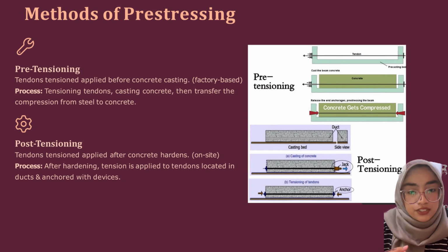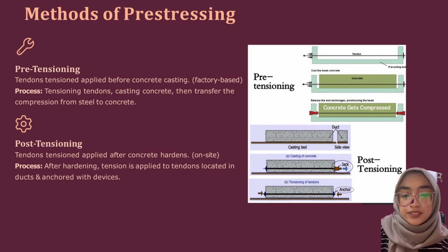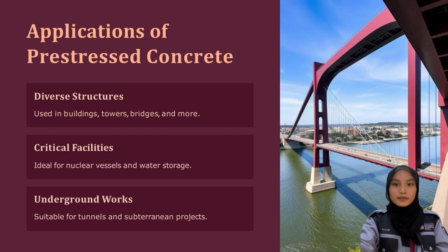Pre-tensioning is often used to manufacture a large number of similar precast pre-stressed concrete elements. An example is a simply supported beam, a one-way spanning slab, and others. Moreover, post-tensioning is often used to pre-stress simply supported and also continuous beams, which have larger spans, and slabs, also a two-way spanning slab, because it has longer spans.